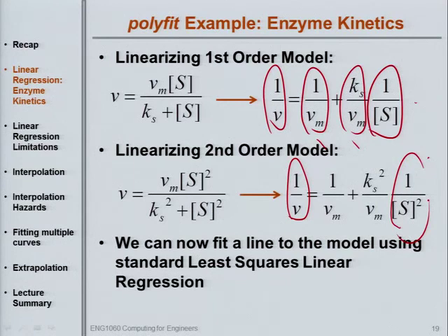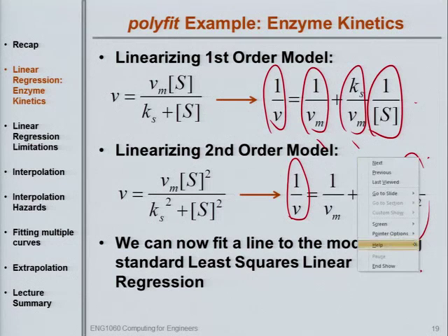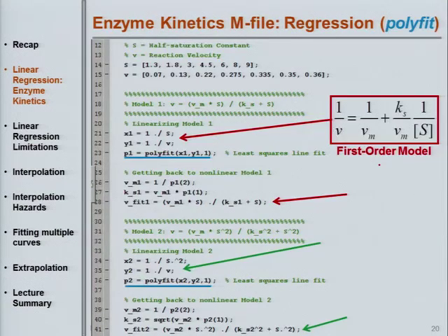But you've also got to pay careful attention to what the formula is actually saying. Is it the sum of x's multiplied by the sum of y's, or is it the sum of x times y? Okay, you just need to look at the formula and interpret them correctly. But there's another way to actually do this curve fit. We don't actually have to use those formula. What we can do, at least if we're doing it in MATLAB, is we can use MATLAB to do it for us. And the way in which we do that is we use polyfit. Okay, there's also a little bit of confusion about exactly what polyfit is doing and what it's giving you back. Okay, so let's just spend a little bit of time looking at that.